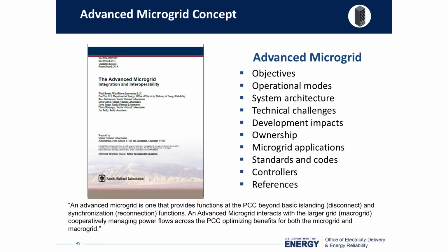So I wanted to introduce the advanced microgrid concept. In the past, the traditional concept is the microgrid disconnects from the utility and provides the reliability and resiliency that serve the customers. With this concept, a microgrid is one that can provide function not only at the point of common coupling, but also beyond the basic islanding and synchronization.